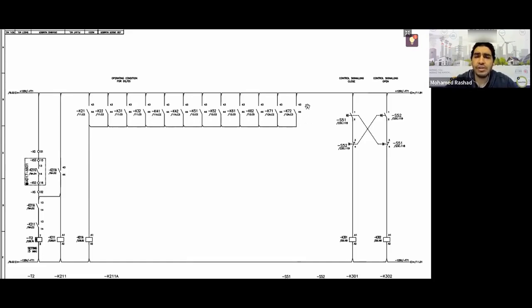These are the 12 contactors that control the close and open commands for me, or these are the close and open commands that will go to the switches. If the switch is fine, great. If I now give a close command to K21, regardless of whether K21 moved or not, whether its motor is faulty or working fine, as long as I give a close command to any switch, the relay will immediately close. Anyway, this relay latches onto itself, right? So this means that this contact will remain closed all the time.